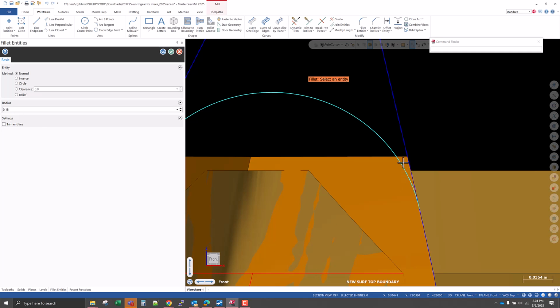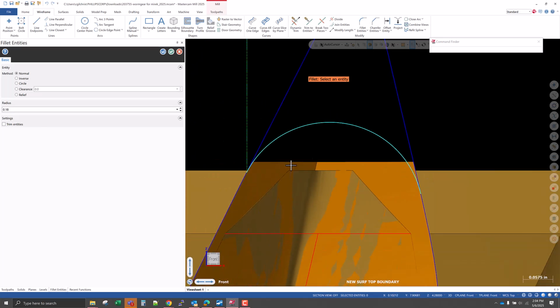You see, I'm not able to get out to that edge of that surface. And the question is, do I allow my tool enough room to move here on the edge? The answer is no. So I like that 150. Let's go back to 150. That's probably pretty good. It may be just a little too large right here. So I could do like 140. I just want to make sure I have enough room to cleanly come off the surface before I transition back to the other side.